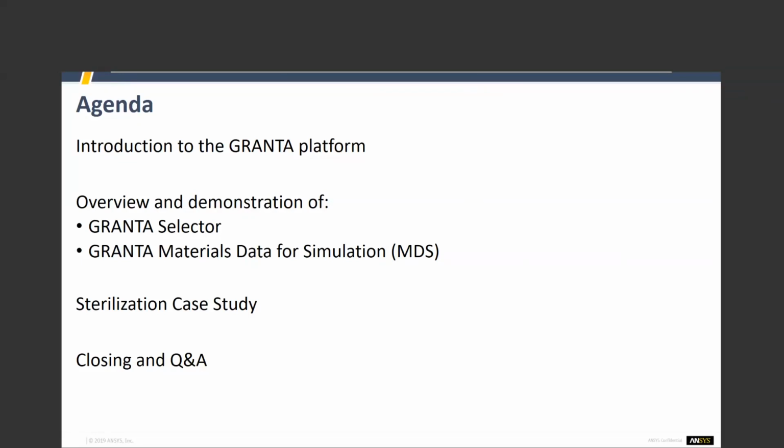But it really enables you to quickly evaluate all of the technical, economic, and environmental performances of different material options. So to put it bluntly, this is a tool that allows you to make educated, informed decisions around what materials to choose for your product design goals and product lines. You'll see that you can compare different types of materials, lots of criteria, filter criteria you can put in, and ultimately it'll narrow it down for you to say, hey, if you're looking for coefficient of thermal expansion between this range and you want to keep the price to X but still meet all your performance goals, it'll quickly identify the best materials for you.